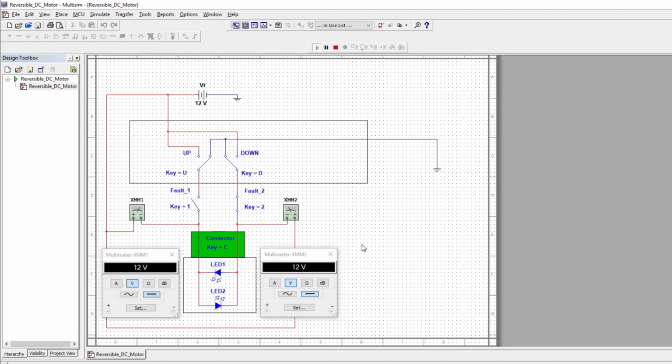What you have to remember, and this is why they're both 12 volts: electricity will take any and all paths getting to where it wants to go. In this case, it wants to go to ground here as far as this voltmeter is concerned. Now, we wanted it to go through to ground through this means. That's what we wanted to check. Electricity isn't always cooperative. You've got to step back and take a look at the circuit. Why is this 12 volts if this is clearly open? Where is this path to ground supposed to be? Well, it's right before your eyes. We wanted it to take this path. It couldn't. We didn't know it. We couldn't tell with this voltmeter that it wasn't.